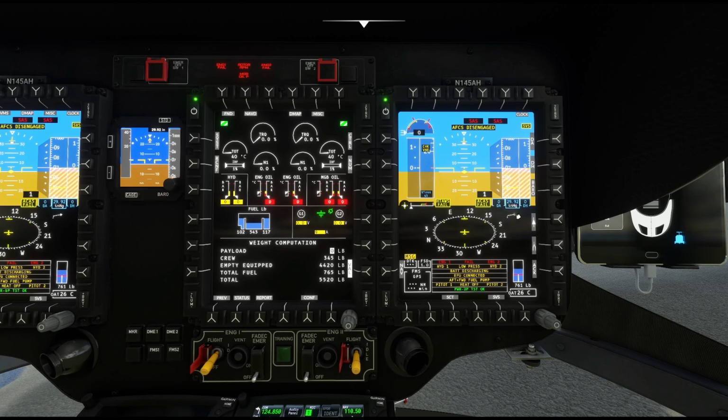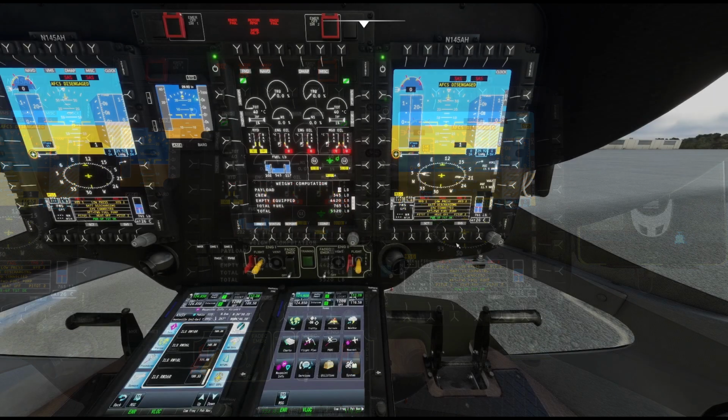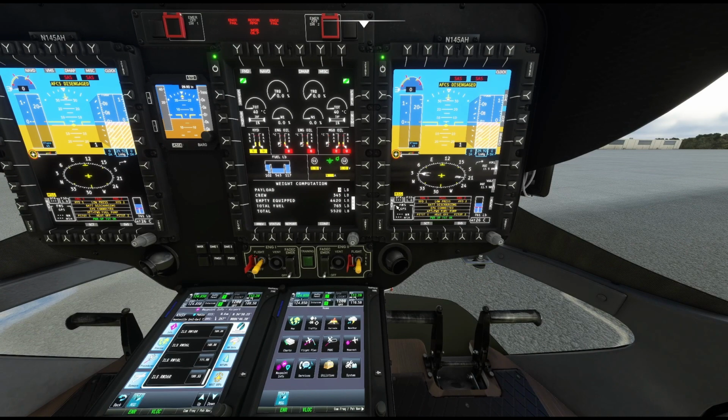The other thing I did not talk about is your wind indicator. So if it's a circle, that means winds are slack right now. Winds are coming from the left side of the helicopter, slightly quartering to the tail, and about 10 knots, because we have a long barb there. A short barb is for 5, right? And then a little triangle on it, looking thing like a filled-in triangle, is for 50. So that'll give us a wind direction and a wind speed. The other thing, so that's pretty much it, I think, for the MFD over here. I think we've hit everything.